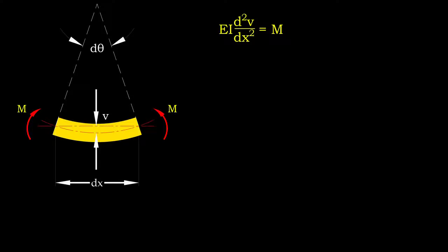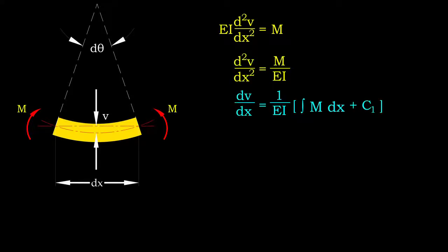With these assumptions, it is possible to determine the deflection of beam using only one equation. As the name suggests, double integration literally asks us to integrate the Euler-Bernoulli equation twice. From the first integration, we obtain an expression containing elastic curve slope dv/dx. Subsequent integration produces an expression containing deflection v. Note that during each integration, we need to introduce a constant, namely C1 and C2.